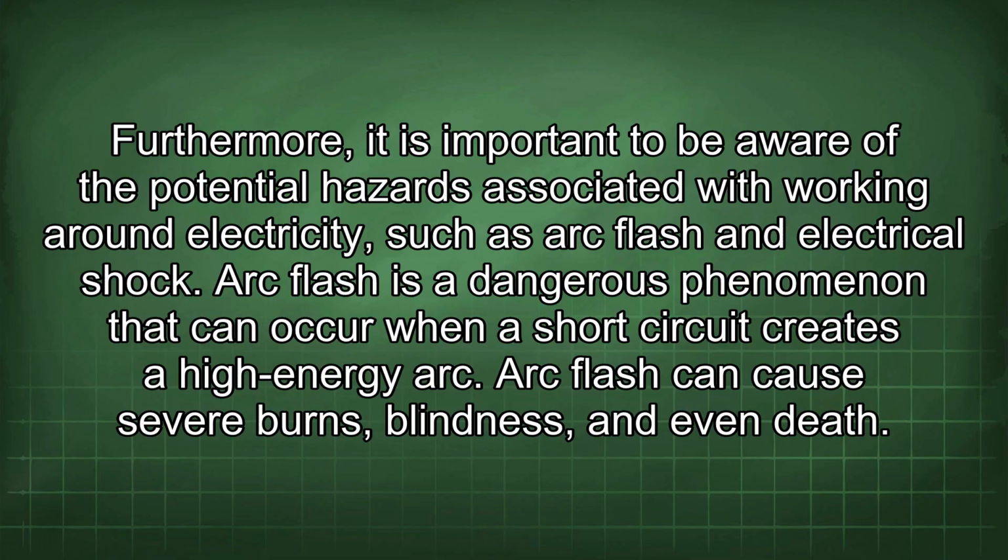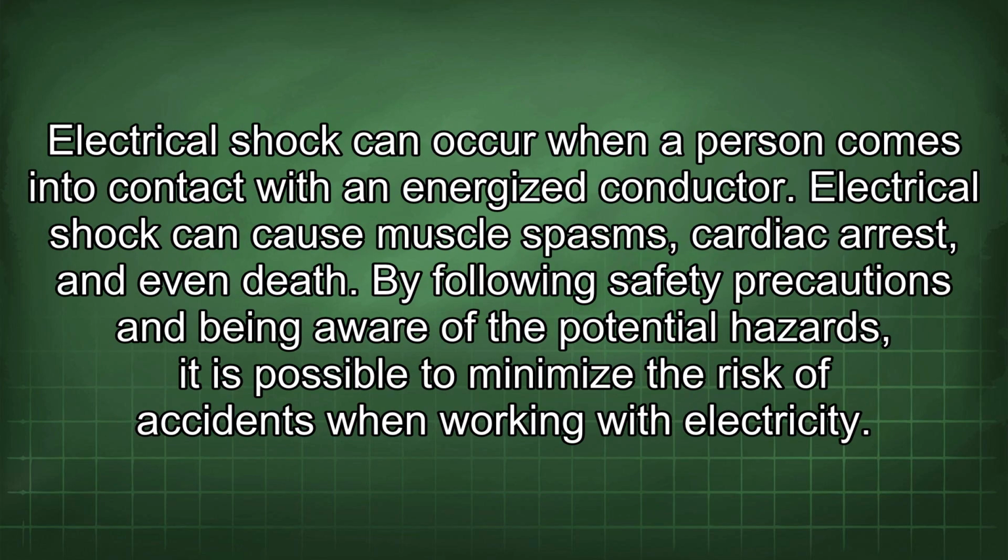Furthermore, it is important to be aware of the potential hazards associated with working around electricity, such as arc flash and electrical shock. Arc flash is a dangerous phenomenon that can occur when a short circuit creates a high-energy arc. Arc flash can cause severe burns, blindness, and even death. Electrical shock can occur when a person comes into contact with an energized conductor. Electrical shock can cause muscle spasms, cardiac arrest, and even death. By following safety precautions and being aware of the potential hazards, it is possible to minimize the risk of accidents when working with electricity.